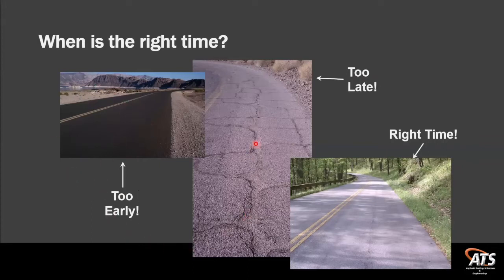But then again, you've got something that may have been out there for 12 years, never been touched. And you've got a lot of structural issues underneath, failures that are happening that cannot be just covered up, hoping that if I just seal it off, it won't continue to deteriorate. So there's a happy medium right in between where your structure is still good, you don't have a lot of this really deep down cracking occurring, and it's not brand new where you feel like you just wasted a lot of money putting a new pavement in.